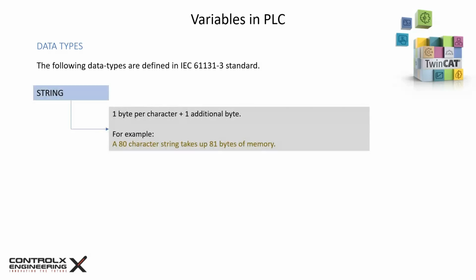String data types can accept any string. The size specification for the storage space allocation in the declaration refers to characters and is enclosed in brackets. If no size is specified, TwinCAT assumes 80 characters by default. This example shows a string declaration used in the PLC.